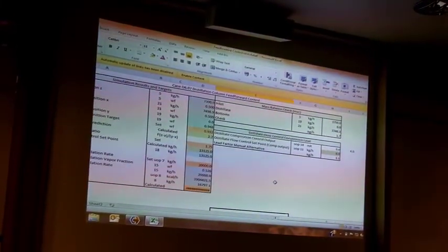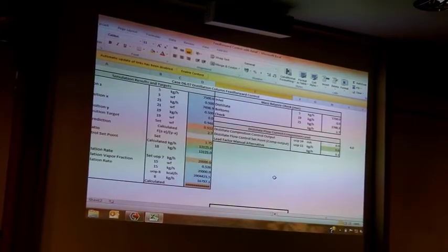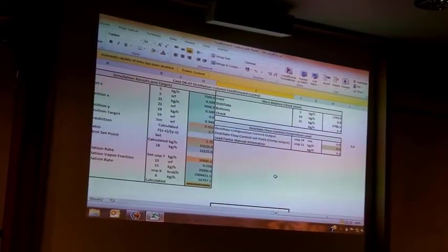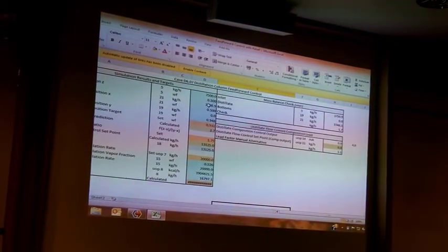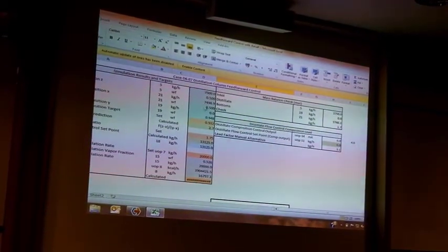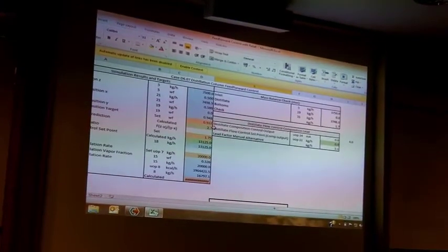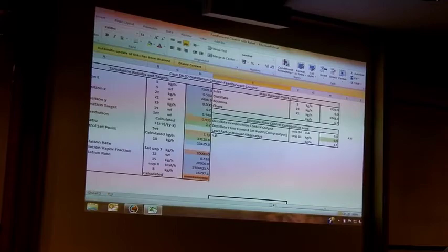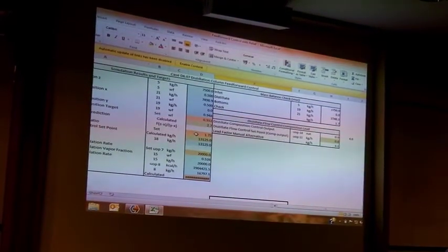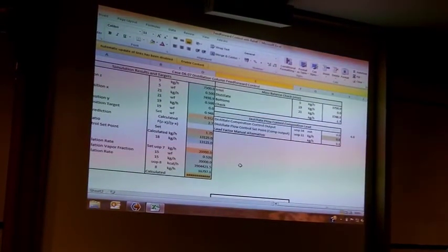What I'm doing here is that Shinskey control model of calculating the distillate flow, and I'm doing all this in Excel. So the blue cells are what's coming out of ChemCAD, and the red cells are what's being used in the calculation to create the set point.